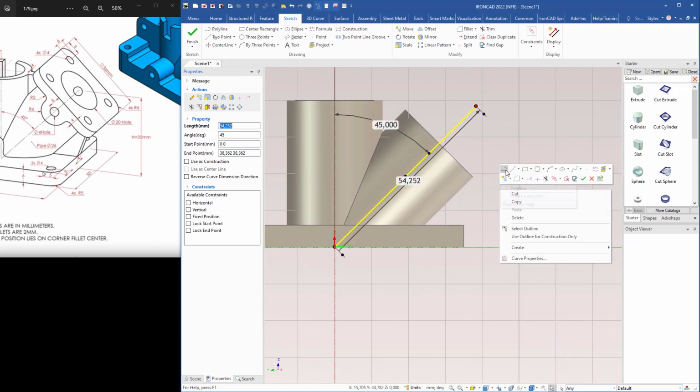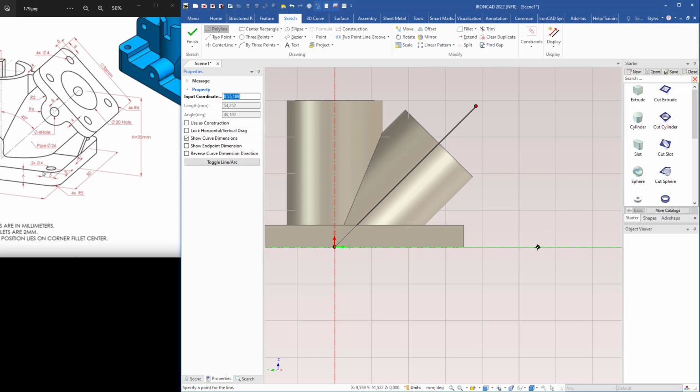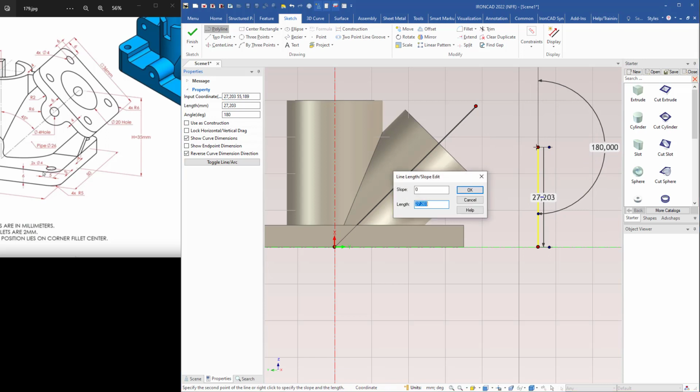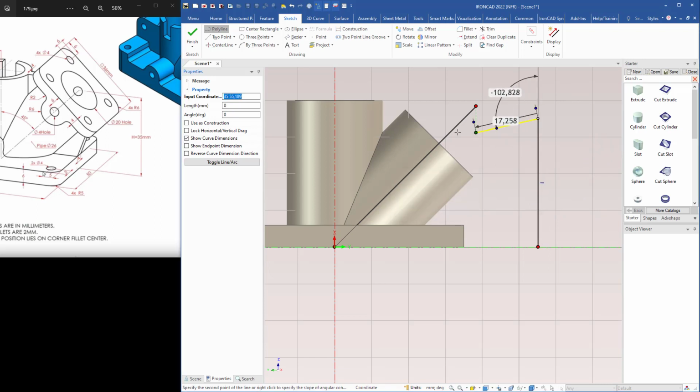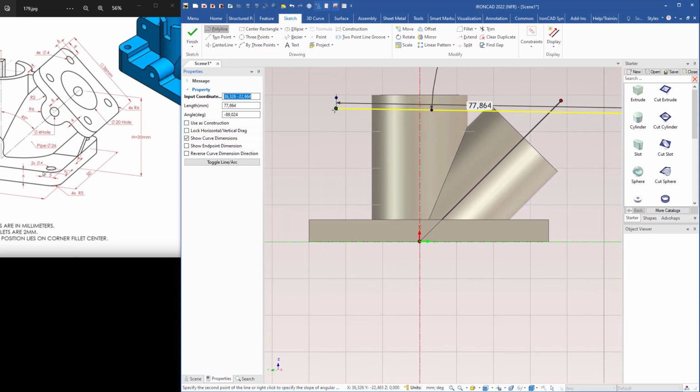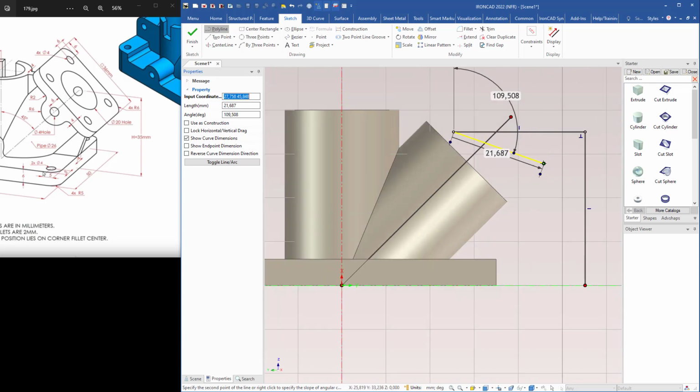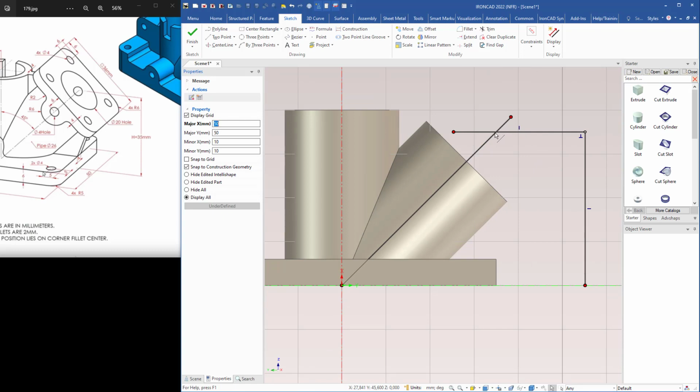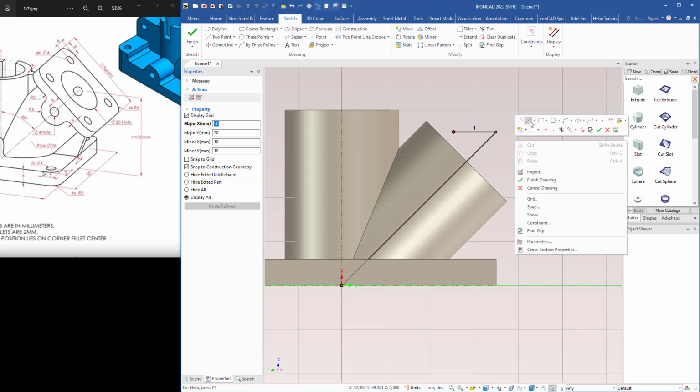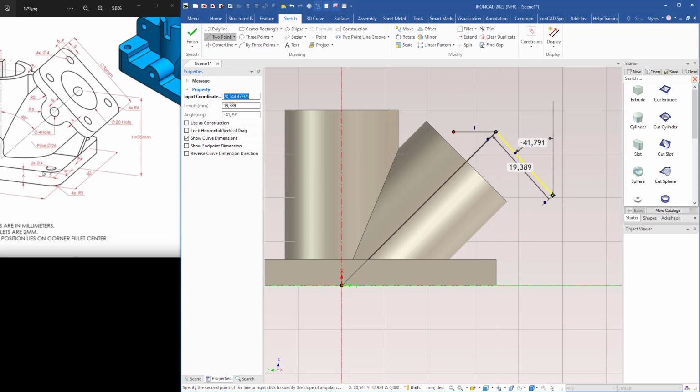And then I right click to select polyline, begin to draw a line from the y-axis, perpendicular to the y-axis, right click here, type 35, and then drag another line perpendicular to the first one, like so. And then we have 35 millimeters here, so I will use trim to trim these lines. Then I right click, choose 2-point line, drag another one perpendicular to the first line there.